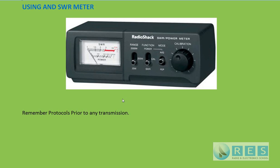Okay, how to measure SWR? Well, because you're going to transmit to measure SWR, the first thing you're going to do before you transmit is check the frequency is clear. If you're not sure, you're going to announce your call sign and say testing, because you're going to transmit and measure your SWR.